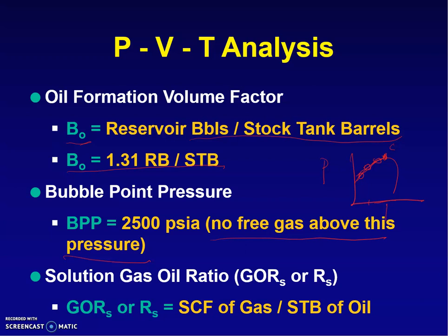And we have solution gas oil ratio, which is shown with RS or GORS as well. The S represents the solution, meaning the solution gas ratio that we are talking about. The unit is standard cubic feet of gas per stock tank barrel of oil. It's basically the standard volume of gas that is dissolved in 1 stock tank barrel of oil.